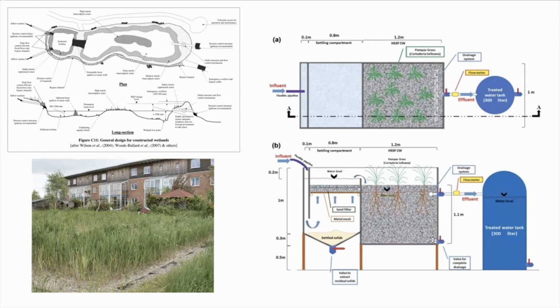And these created natural systems come along with all the associated maintenance issues, such as mosquitoes and algae bloom and whatnot. And the maintenance for a constructed wetland is typically more intensive than a retention pond. However, a benefit of that increased maintenance is that, for example, when weeds die in the winter, you're able to harvest that for fertilizer. So there are added benefits. It's sort of like adding another farming system to your project.